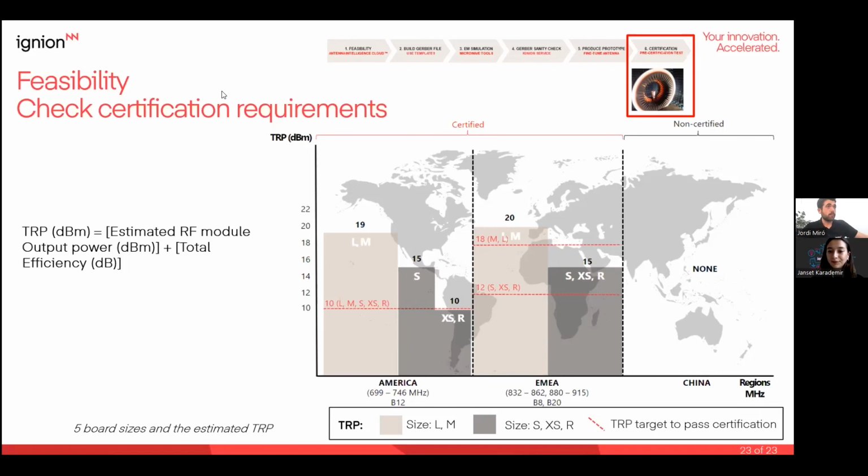I think polycarbonate material is the last thing that you will consider in your design. I saw in other customer devices that polycarbonate may shift the antenna response a bit, but it will only add some losses to the system, so it might affect the total efficiency.